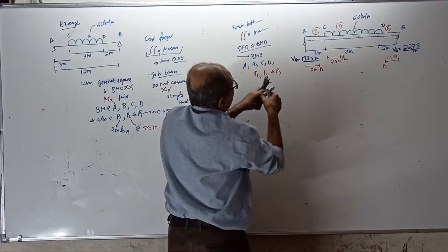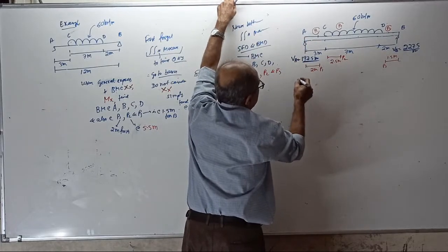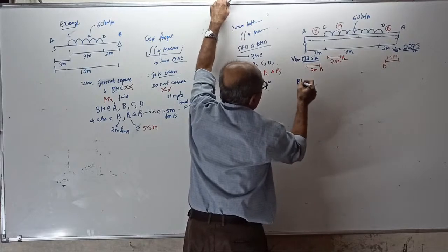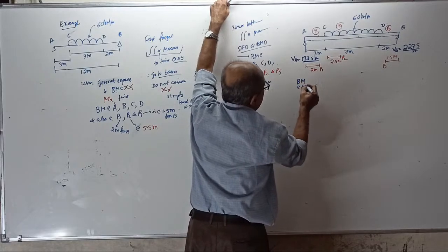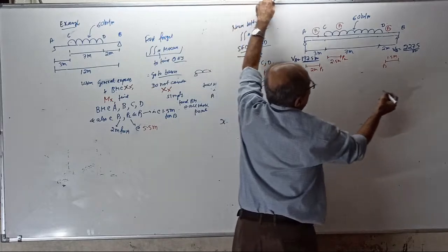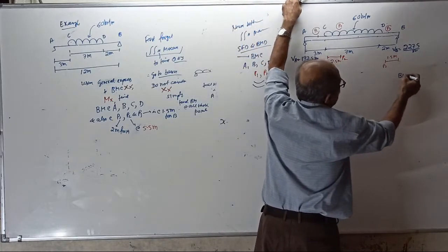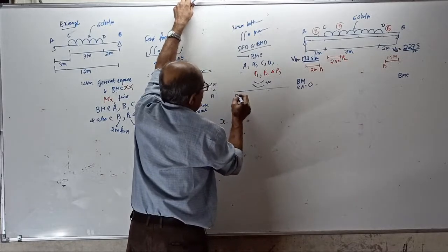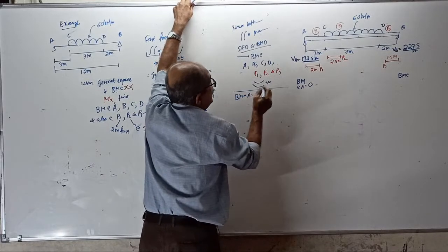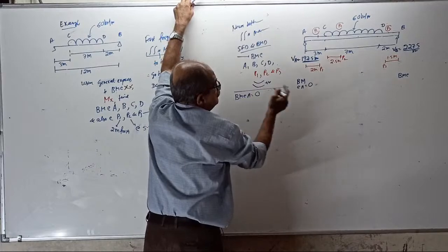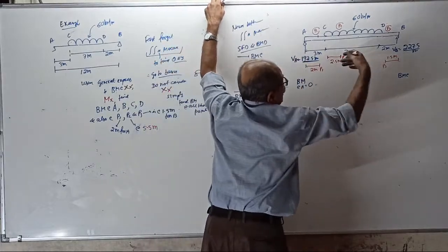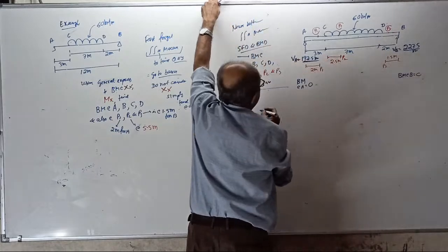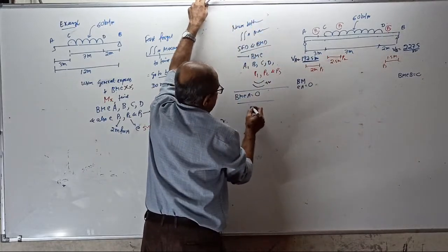Answer correctly. I want all sagging positive. I want the bending moment at A, 100% zero. I want the bending moment, you do in correct order. You write here, start. Bending moment at A, look this side, 0. Bending moment at B, look that side, 0. Then write, you show the calculation.